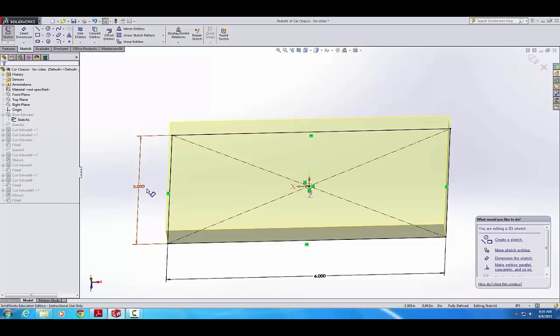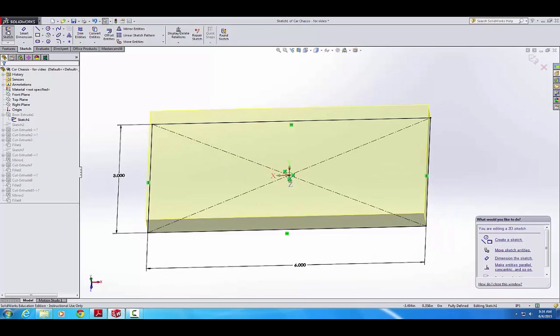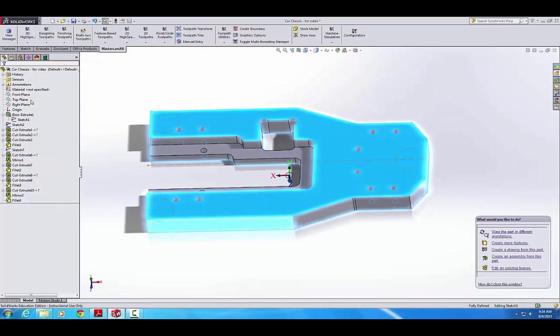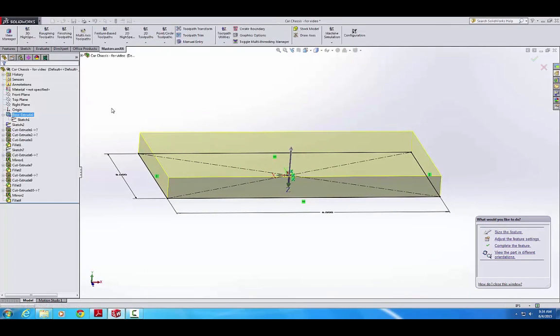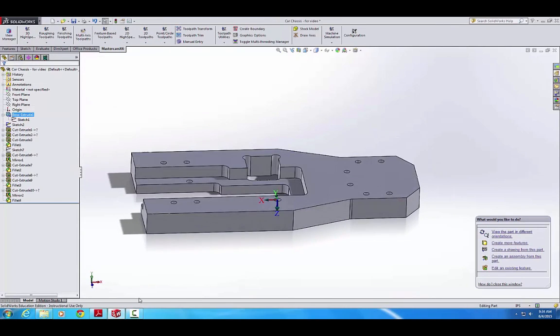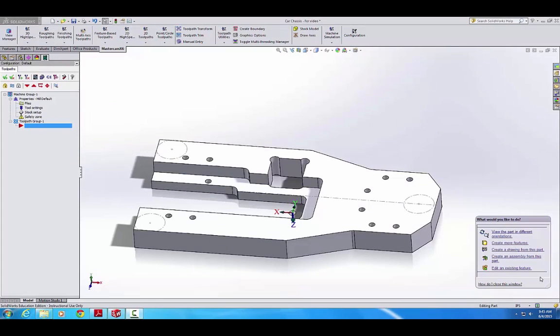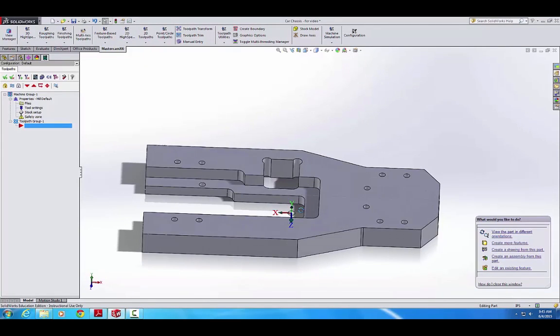So in this case, I had a width of 3 inches, a length of 6 inches, and also a height of ½ inch. So that is reflected in my SolidWorks. So our SolidWorks is looking good. The dimensions of our part match the dimensions of our stock, and it is realistic to machine. Next two steps, set up our origin and set up our stock in MasterCAM.